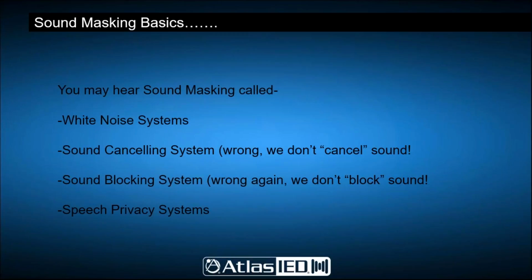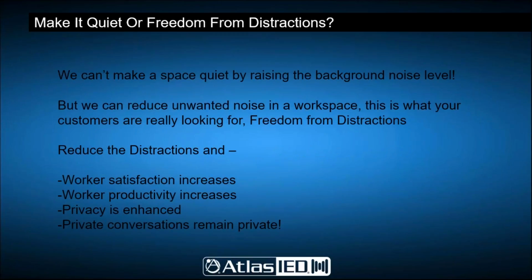Sound masking basics. You may hear sound masking called white noise systems. This is just one variation of what masking can actually do. Typically about 90 to 95% of masking projects out there for any facility is going to be running a pink noise system. White noise is just one variation of what it is. Sound masking systems, sound canceling systems, which we're not doing that.